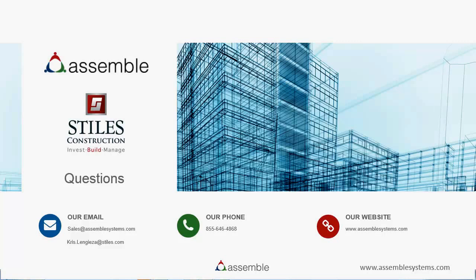All right, thank you. Another question regarding shared parameters. Do you need the shared parameters to be in the published model, or can they be in another model published to the same project? Yeah, so they need to be in the model that you're publishing to Assemble. By pushing that one model with the shared parameters, it would only have those parameters attached to that model. So if you push, say, 3 models to Assemble, and one of the 3 models had the shared parameters in it and the other 2 didn't, only those elements that came from that model would have those shared parameters available to it.